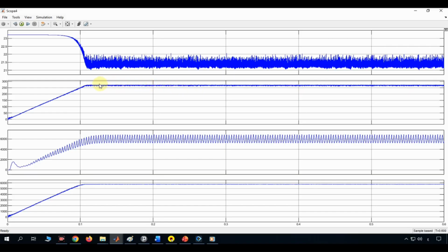Rather than snapping the system's voltage up to its full operating value instantly, which could cause a large current spike or stress the components, the control system ramps the voltage up gradually over that first 1/10 of a second, then holds it steady once the target is reached. Given its scale, in the hundreds of volts, this is most likely the array's operating voltage, ramping up to the point the maximum power point tracking controller has settled on as the best operating voltage for the current conditions.